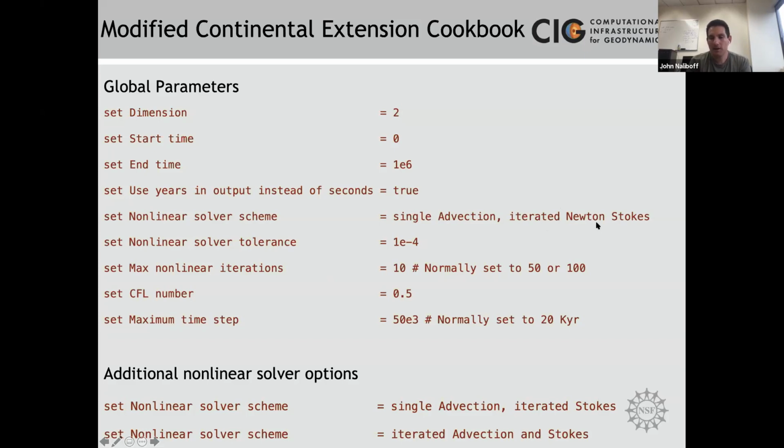You start off with an initial solve based on a background strain rate at the very first time. Through that, you then have a velocity for the model. Then you go back, update all of your material properties to account for the new velocity field, and then calculate the solution again.